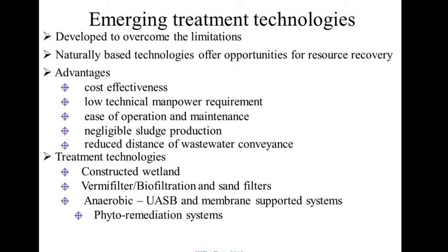The structure of the vermi biofilter is gravel supported, with sand and with soil for the earthworms. The working happens at the top layer of the soil, where the earthworms survive and organic matter oxidizes. After water passes through the filter, it gets purified.